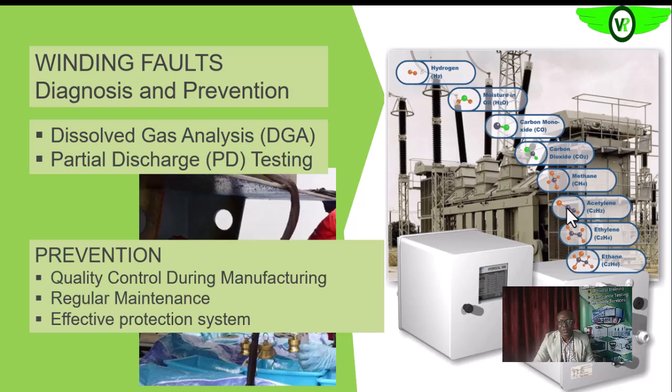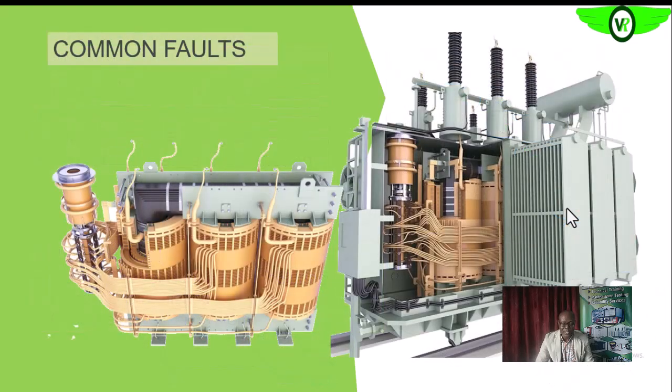We also want to maintain a regular inspection schedule of the silica gel on the transformer to see if it is saturated or not. If it is saturated, we want to change the silica gel, because once it is saturated, it means moisture will be admitted into the transformer. For very large and remote transformers, once the saturation gets to a certain level, that could be indicated in the control room so that we go for silica gel change out.